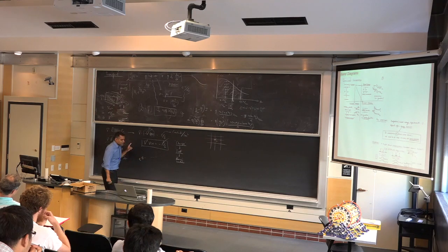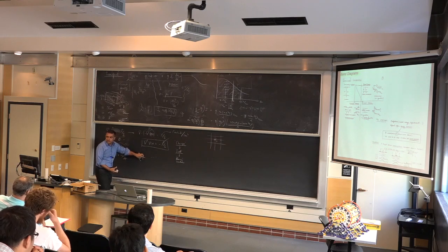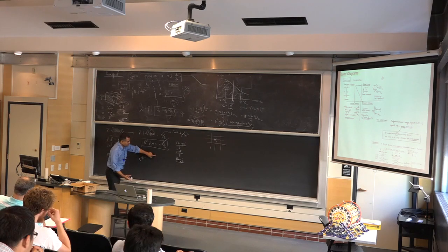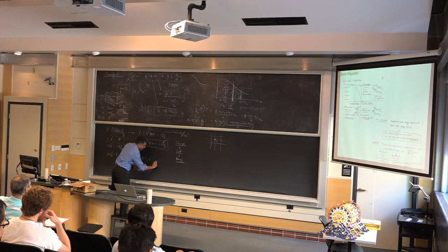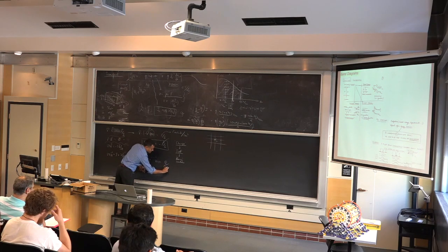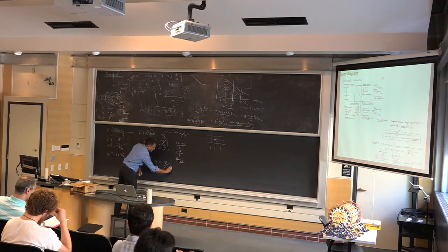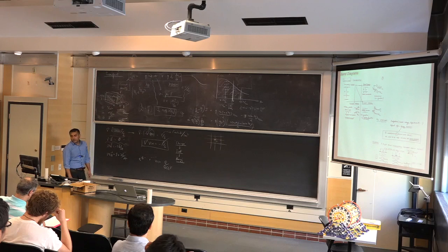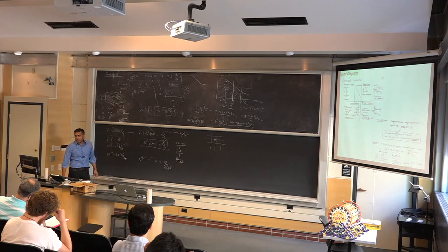Well, this problem we have solved. It's a 3D problem with one point charge. What's the potential at any point, or what's the field at any point? We know that. The potential at a distance r would be q over 4 pi epsilon, but you are in a semiconductor, so I would use the dielectric constant of the semiconductor, times r. That's your potential at a certain distance r. And then the field would go as 1 over r squared, the inverse square law. So that is easy.